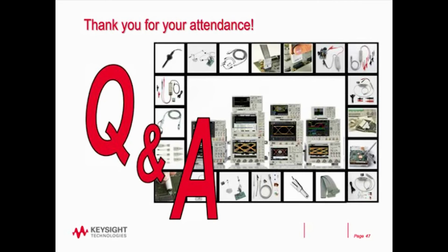Are these probes for the AC current all compatible with other scope manufacturers? Some of them are. Some of our probes have what we call the auto probe interface, and that's a Keysight auto probe interface. And in those cases, those probes can't be used. But also some of our probes have a standard BNC connection. And some of them have battery operation or an external power supply. Those particular probes can be used on any vendor scope.